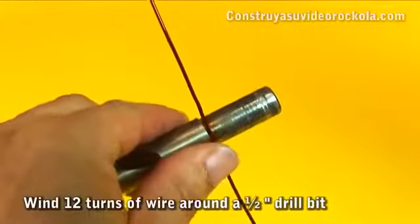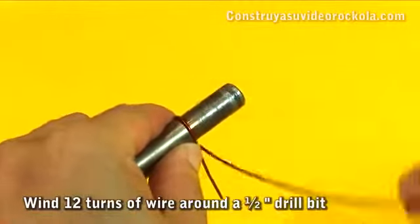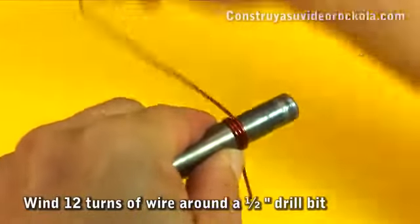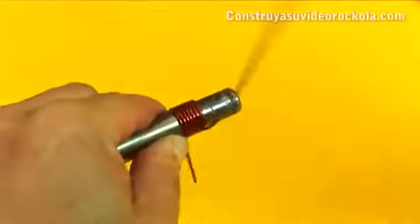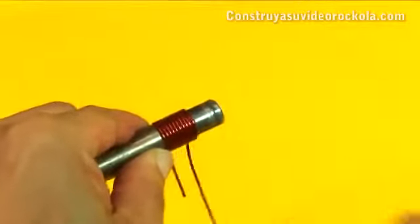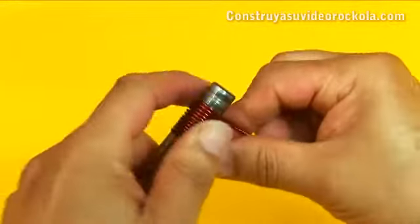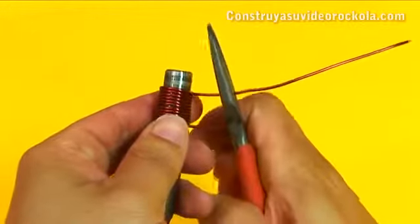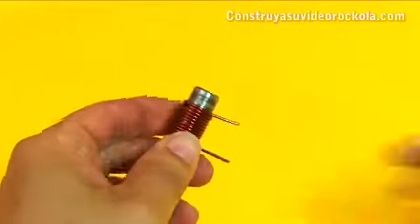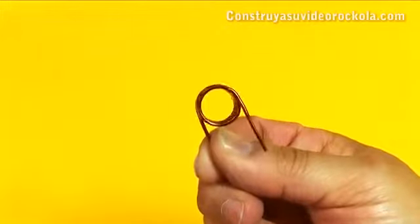Assembly. We will begin by making the coils. We take enameled copper wire, and around a 1/2 inch drill bit we roll up 12 turns. They must be well aligned, and without spaces between one turn and another turn. We cut the excess wire. The coil should be as perfect as possible.